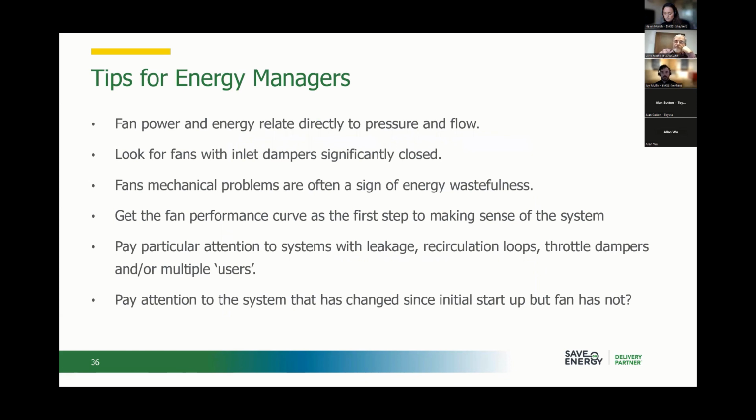If you're looking for fans that are good opportunities, look for ones where the inlet dampers are significantly closed. I showed you that one example with a fan that had way too much margin on it. And so if you've got dampers that are quite significantly closed, those are likely good opportunities. Maybe variable frequency drive opportunities, maybe smaller wheels inside the fan. There's more than one way to deal with some of those kinds of issues.